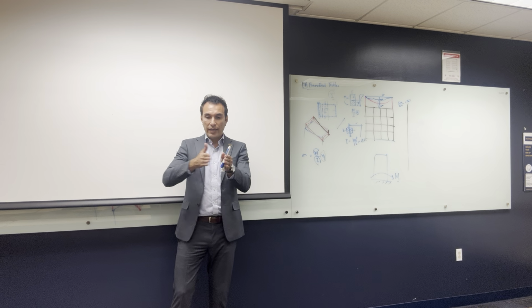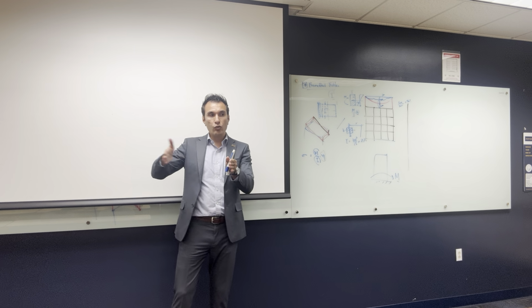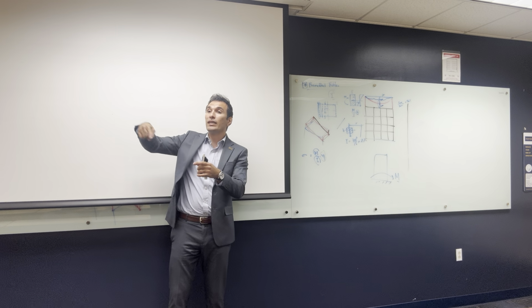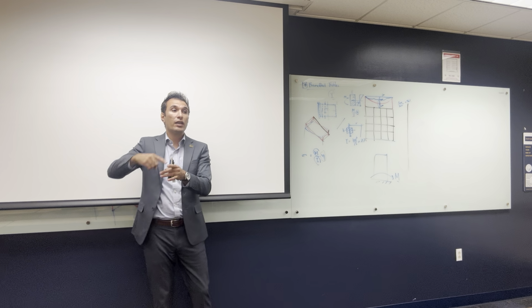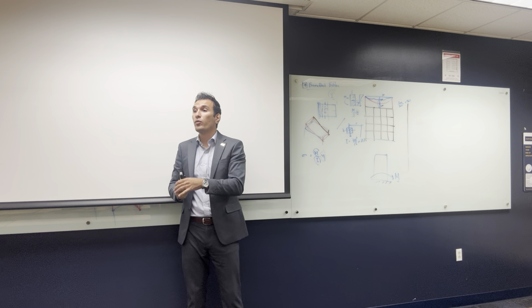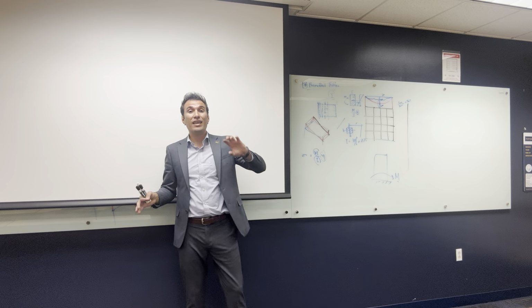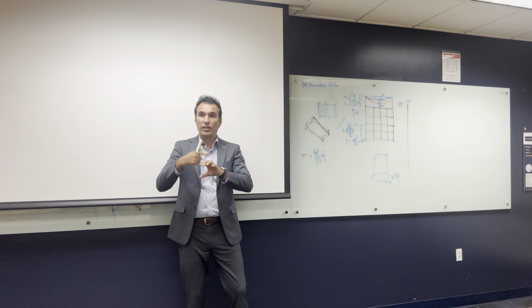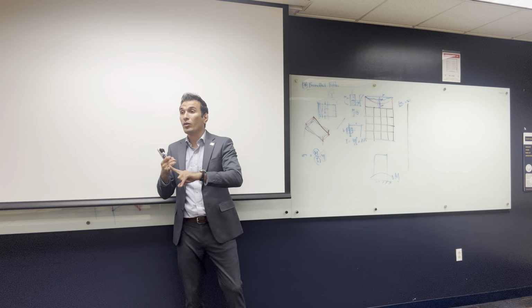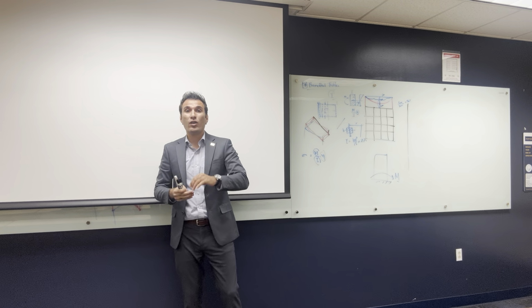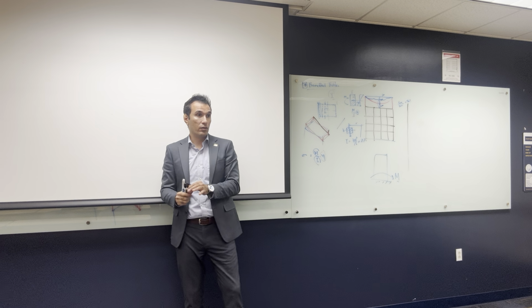For each system, X is going to be system 1, 2, 3 up to 10. And you will show me the shear lag, how the shear lag is getting less or getting more for each system, and how the drift is going to look. That's what we call a parametric study. We're going to see how a specific parameter impacts the system performance. When I say system performance, we're talking about the shear lag, the inter-story drift, and the total drift of the building. We are going to look at all these separately, okay?